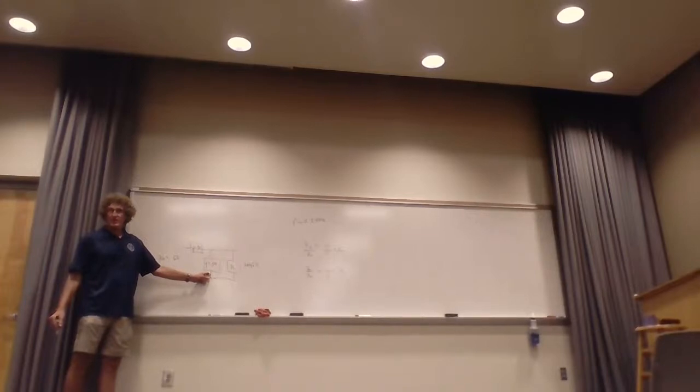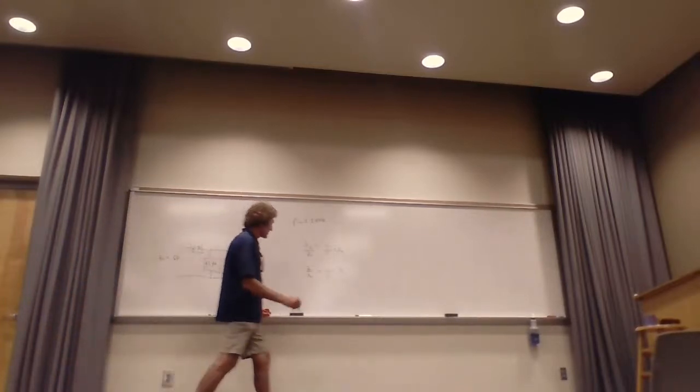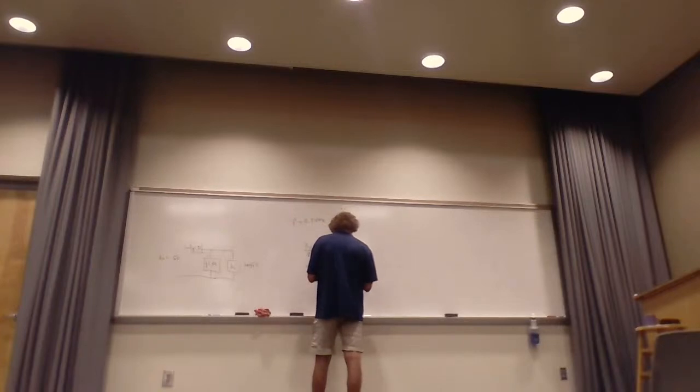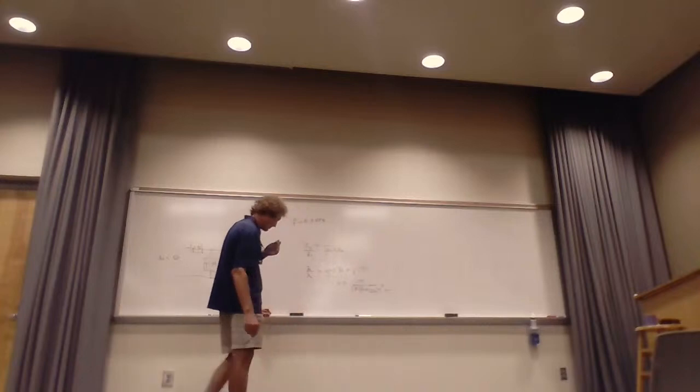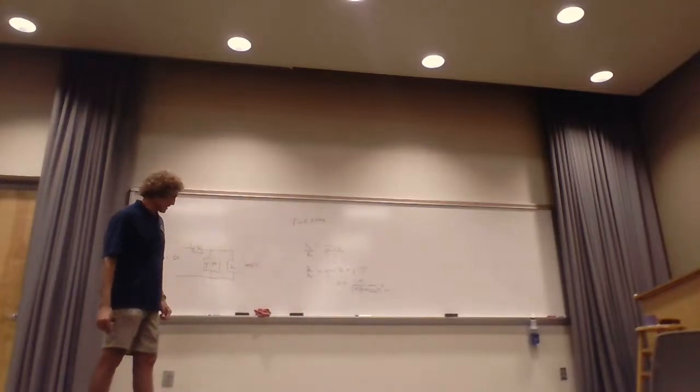Y'all follow my train of thought on this? So that's equal to j1.34. And that means the value of C is simply 1.34 divided by Z naught, which is 50, divided by omega, which is 2 times pi times 2.5, that's 2.5 times 10 to the 9th. And that'll be the value of capacitance. And looking at that, that looks like it's picofarads.